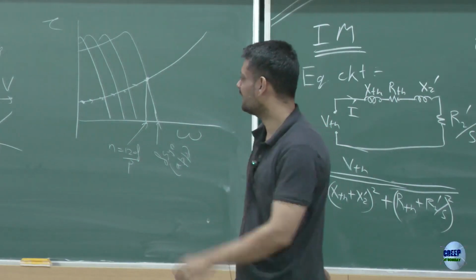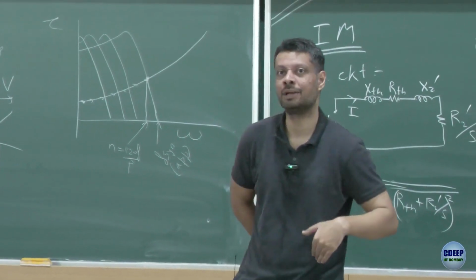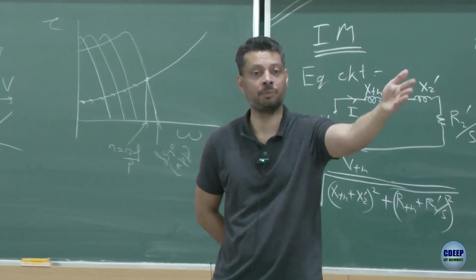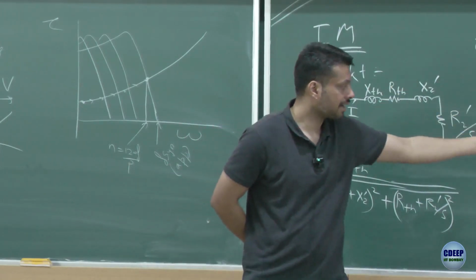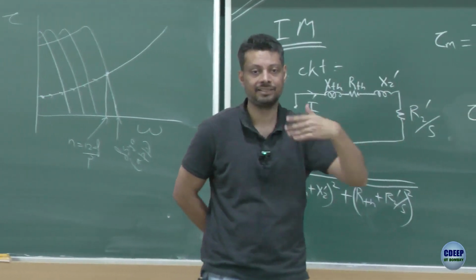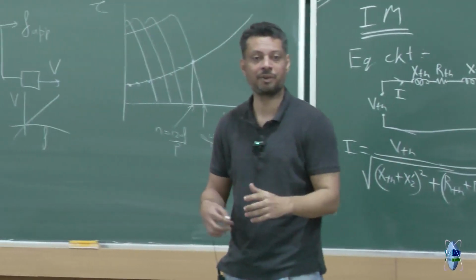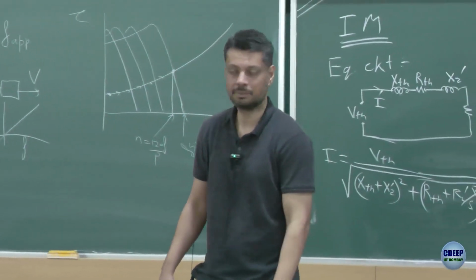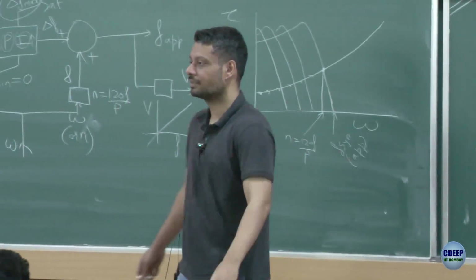Yeah, main reason is to make sure that you are not really going ahead of the actual operating speed too much, because if you go ahead too much, all the problems of high current, low starting torque, everything sort of comes back, right. So mainly it is to restrict you from going too far ahead of where you are now, right. That's the main reason. Okay, this doubt is answered, so we will stop here.